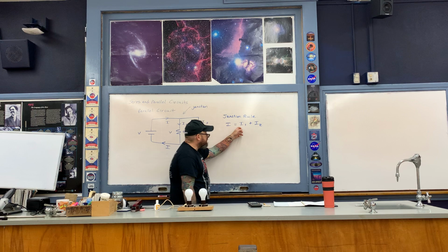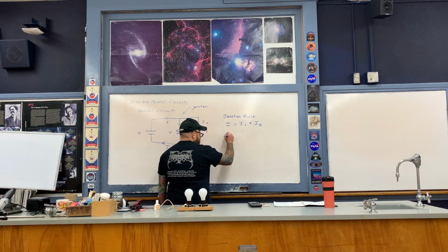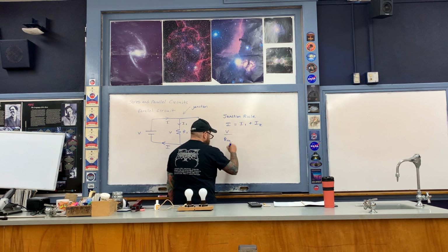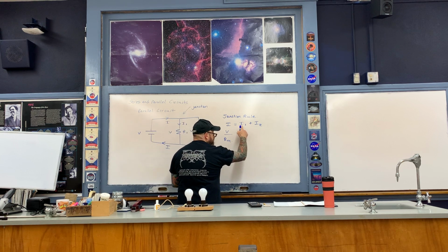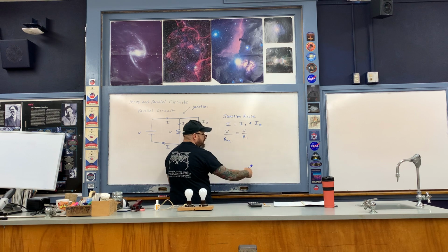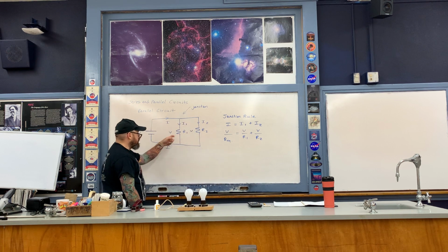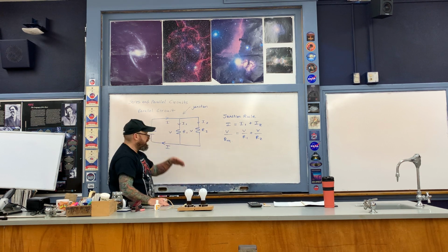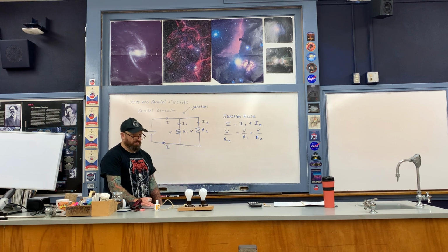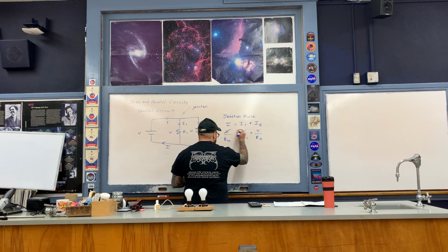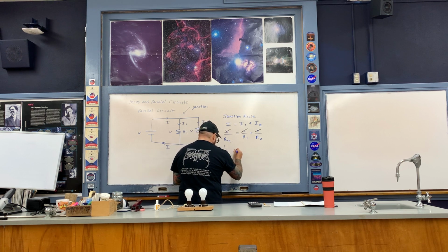So now let's go ahead and replace all of these with Ohm's law. So first of all, the current I, I'm going to write as the voltage V divided by what is referred to as the equivalent resistance. And then on the right-hand side, we have the same voltage V divided by resistance R1. And then right here is the same voltage V divided by resistance R2. Once again, the voltage across each of the resistors is the same as that of the battery, because all of this is an equipotential surface and all of this is an equipotential surface. Okay, notice that the V's all cancel out, like so, and you end up with an expression that is written like this.